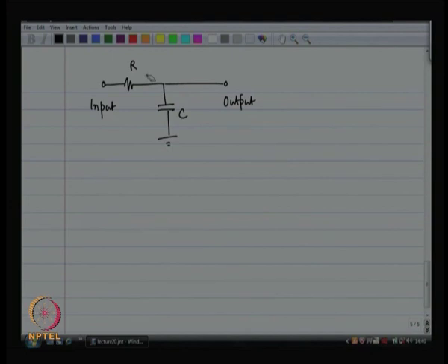To do this, we have to replace the resistor with its equivalent model, which has a noiseless resistor and the noise voltage source, and then we have to work our way. So, let us see what can be done. We are going to replace the resistor with a noiseless resistor in series with a voltage source. This voltage source has a mean squared noise voltage of 4 kT df times R.